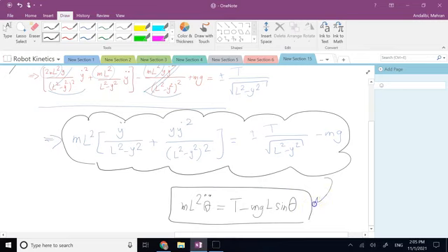Compare these two together, and you'll feel that when you choose the wrong coordinate, when you choose the wrong generalized coordinate, it can change your differential equation, the governing equation of motion, to something that is much harder to derive, much harder to solve, and it's not going to behave so nicely, because here you have to decide in each motion whether you choose the positive side or the negative side. You have to keep track of that.